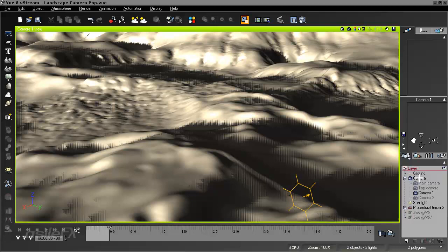So I want to create about a 5 or 6 second animation. What we can do is expand the timeline view, holding down Control on the keyboard, and then if you right click and then move the mouse up or down, you can scale. If you right click, you can pan the timeline, and that way we can keep everything in view or shown.